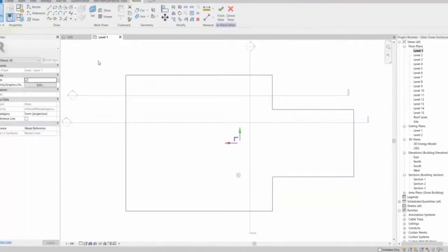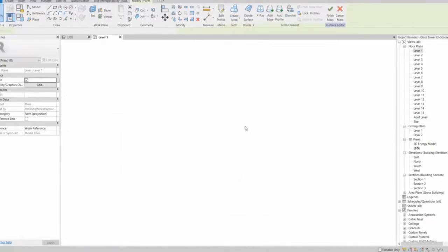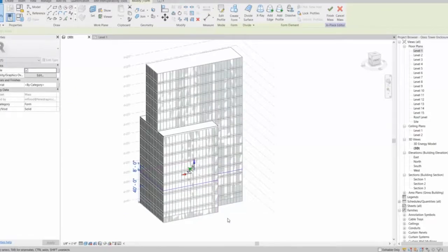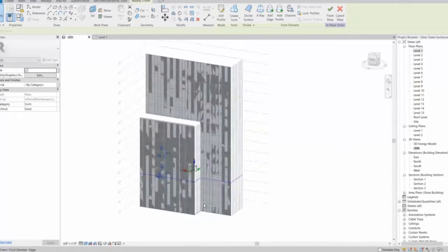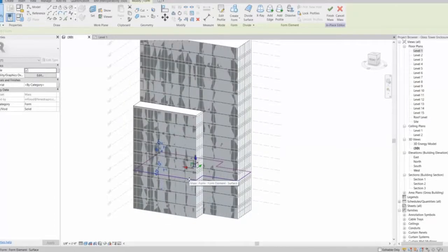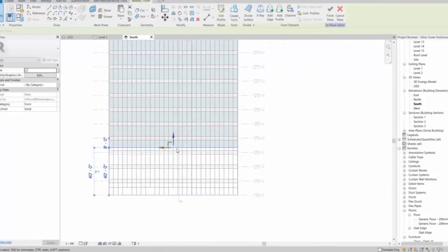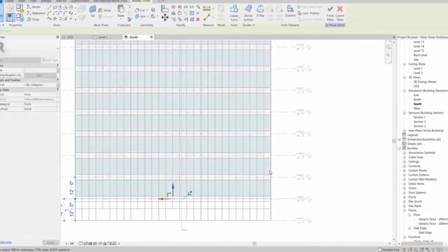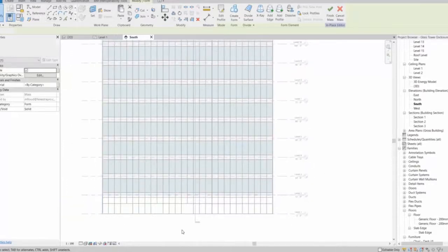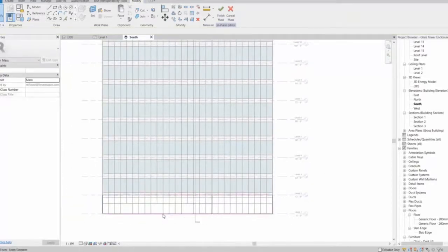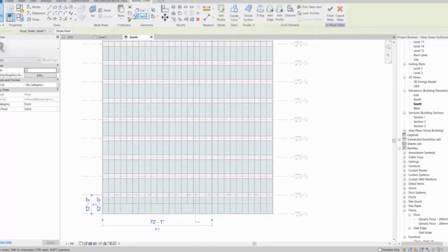Let's go back to the 3D view, and we really want to model just from level 1 to level 2, so we're modeling level by level. That gives us more control later over different surfaces. So we'll just bring it down to level 2, and then we can just copy and paste these mass zones to the next level. So we're going from level 1 to level 2 there, and we'll just select all of that mass zone, and we can just copy and paste to align levels.